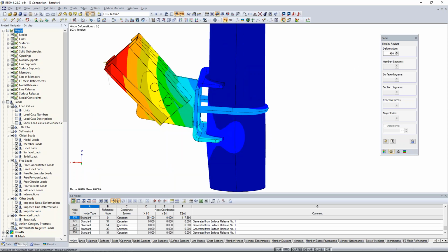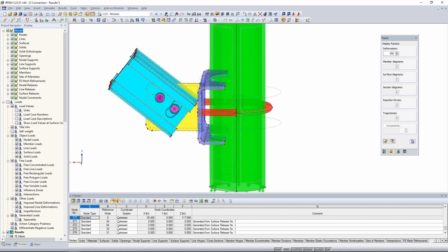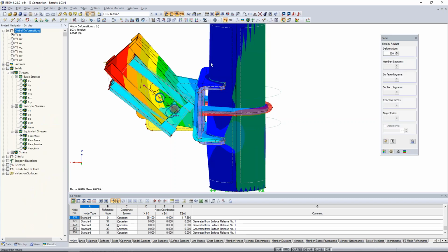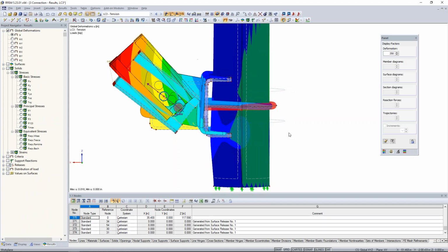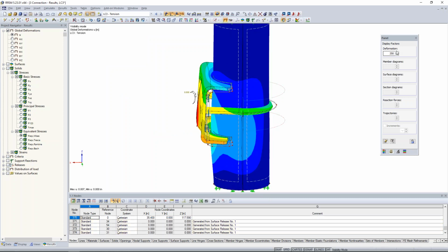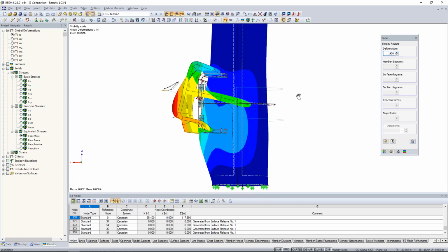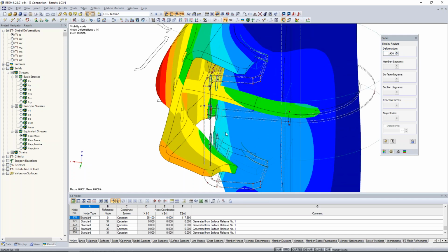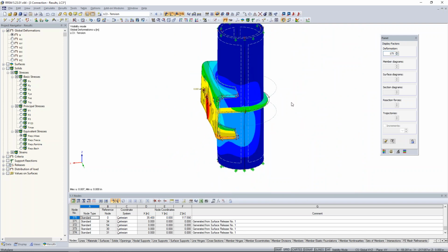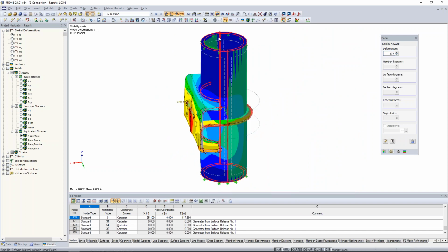And of course, we can take a look at our tension case here. And if I cancel the visibility, and actually let me turn back on my model. If you remember, we just have this load being applied right along the same orientation as the members. So taking a look here at the results and the deformation, I'd like to just show you guys once again what's kind of happening with our relationship here with these elements. And you can see that when we turn this into a wireframe view and we increase our deformation here, once again, we have this element, the plate element, kind of pulling away from this pipe. So everything has been correctly defined with these deformations exactly as we would expect. So definitely the behavior that we'd like to see.